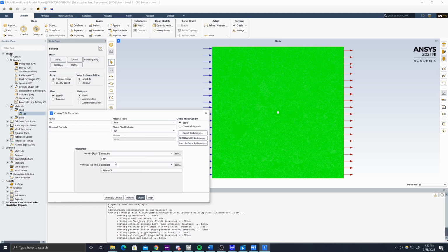In the problem, we were told to have 150,000 to be our Reynolds number. After going through air tables to get the closest value to that, we are going to use a density of 0.21324 and a viscosity of 1.4216 times 10 to the -5th. I'll run through the rest of these quickly since we've seen this before. If anything changes, I will show on the screen.